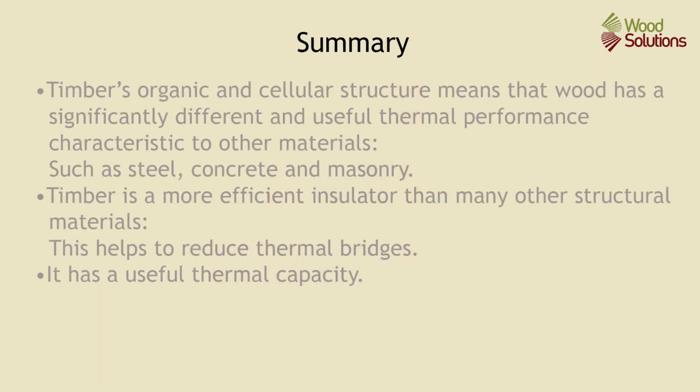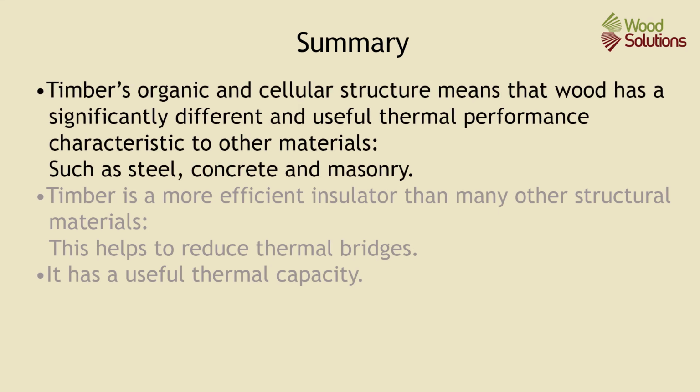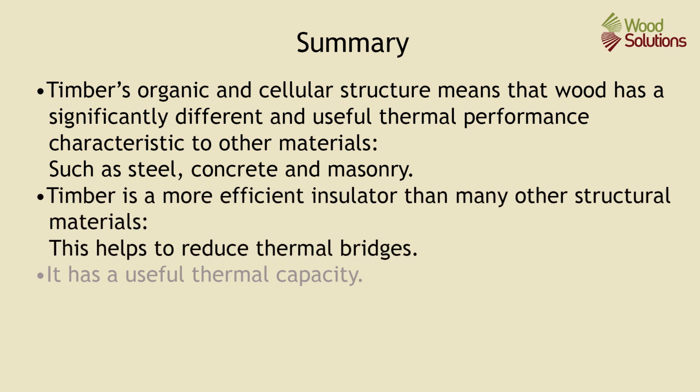In summary, timber's organic and cellular structure means that wood has significantly different and useful thermal performance characteristics when compared to other major building materials such as steel, concrete and masonry. Timber is a more efficient insulator than many other structural materials. This helps to reduce thermal bridges, and it has a useful thermal capacity and can contribute to a building's thermal mass.